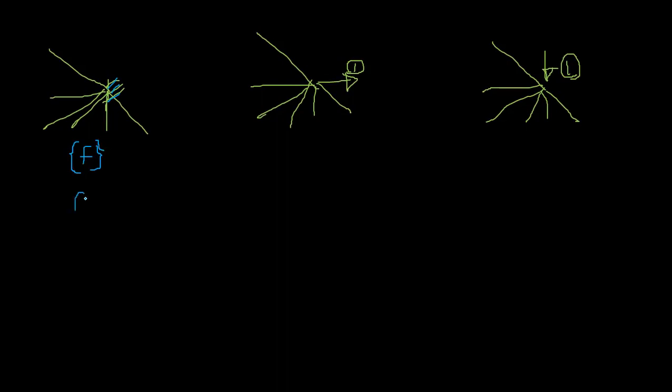Then the member forces in each member, AR. That was 0, right? There is no temperature effect or second-order effect in any member. So that was 0. Here, sorry, here it is stiffness. Why? We are applying a unit displacement and the corresponding force is stiffness. Stiffness is okay. We found this and we found the actions as well.